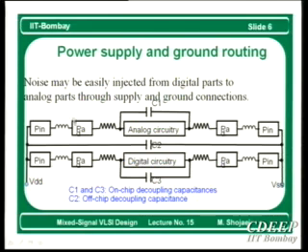Now, we want to have the same AC, meaning that essentially their difference we want to be constant, not DC. Essentially the difference to be constant. Because suppose I have a VDD and VSS which follow each other, that's okay. Suppose even slowly they are changing. It's just a matter of level shift. After all, nothing happens, as long as external circuitry doesn't suffer, that is fine.